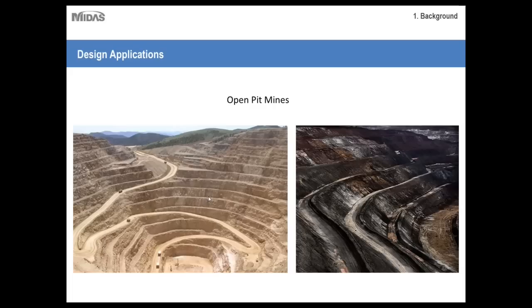Most walls of the pit are generally dug at an angle less than vertical to minimize damage and danger from rock falls. This depends on how weathered the rocks are, the type of rock, and how many structural weaknesses occur within the rocks. Because these are typically excavated along rock lines or rock layers, there isn't too much need for structural supports.